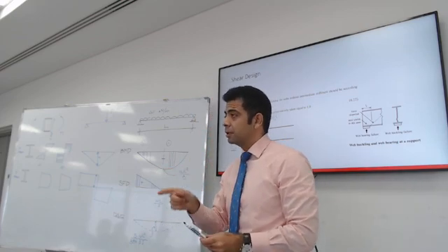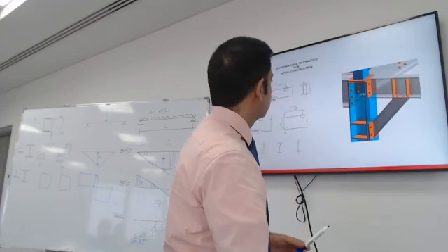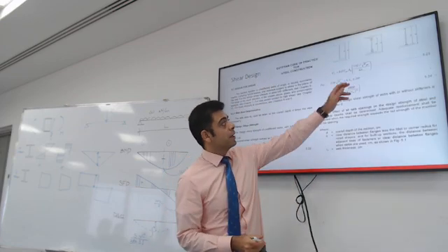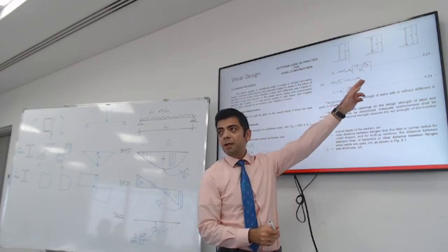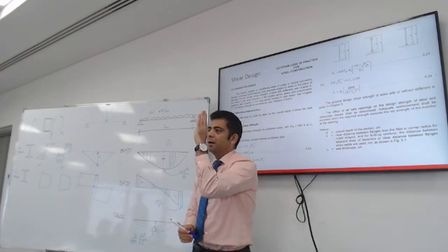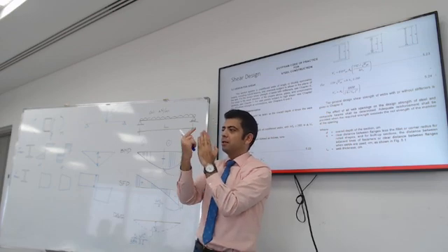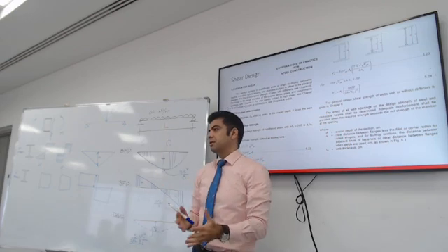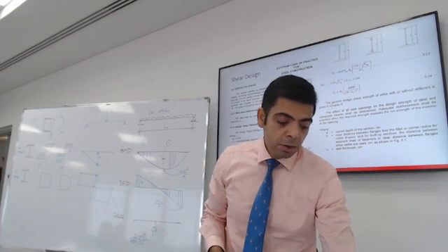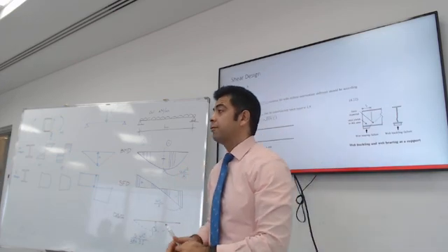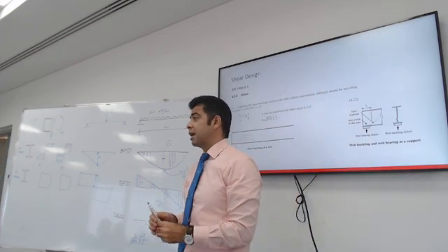That's actually a great question. You can build up sections. Look at the section in the middle. You can get a vertical steel plate, a horizontal steel plate, and put a steel angle on the side and make up your own section. So the code gives you the room and flexibility to design your own sections.